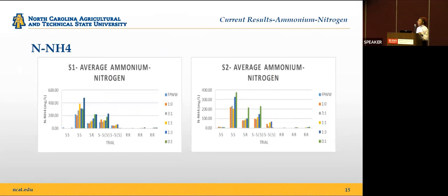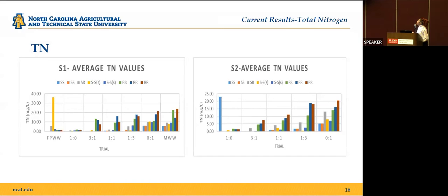And we also did ammonium nitrates. So in this system, we can also see that ammonium is also being removed during the treatment process. And during all of the simulated wastewaters, whether we used it synthetically or real wastewater, ammonium still has the ability to be removed from the system. The same can be seen with TN. We see that TN is also lowered during the first phase, in the second phase, after the first phase, after aeration, during the treatment system.